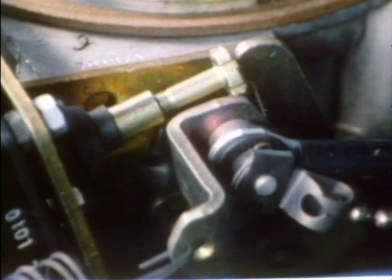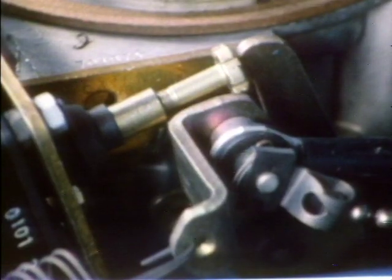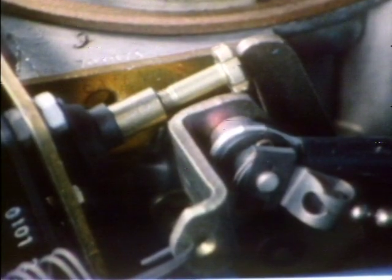Also at idle, the ISC provides increased throttle opening to compensate for changes in engine load, allowing for a more consistent idle speed. The last function of ISC control is to provide a partial throttle opening during deceleration to prevent engine stalling and control emissions. This feature acts similar to a dashpot used on some carbureted engines.